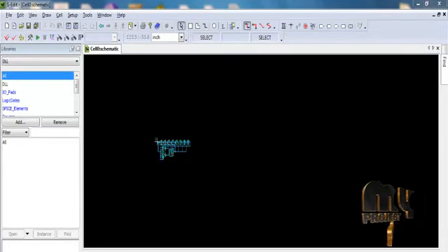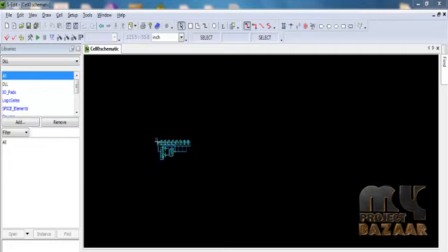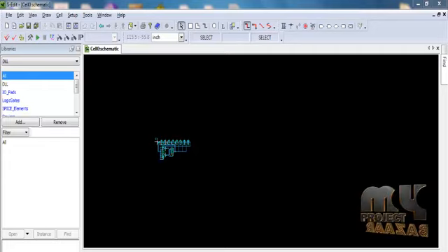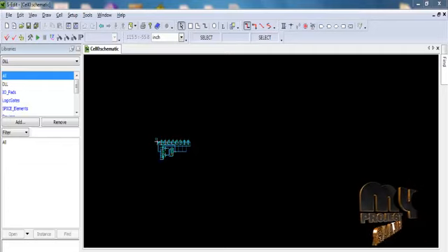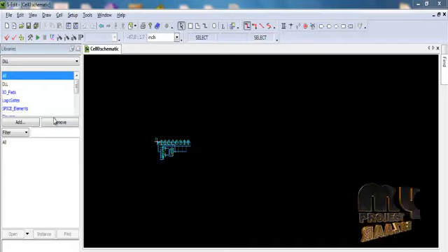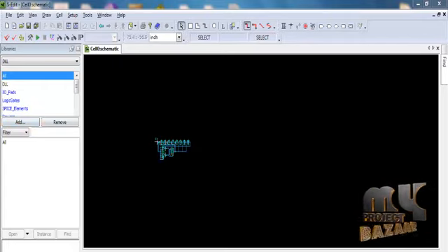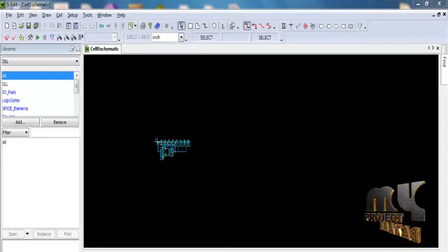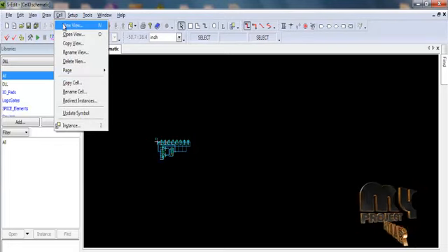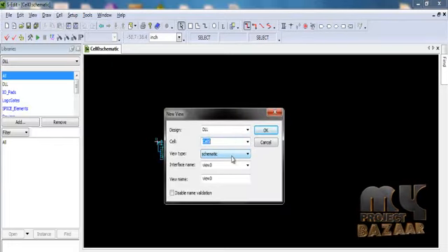Now we are going to discuss the running procedure of our product. Our product can be implemented in Tanner EDA version 13.0. Open the tool window and create a new file from the File menu. After creating the file, add the library from the Add option. After adding the libraries, create a new cell from the Cell menu, using New View to create a new cell.